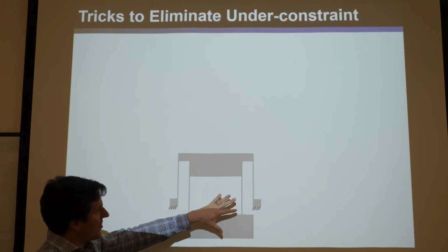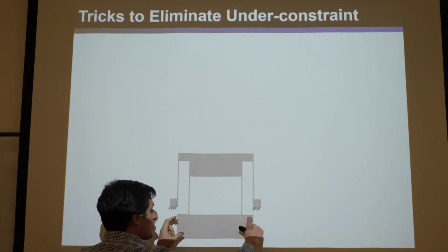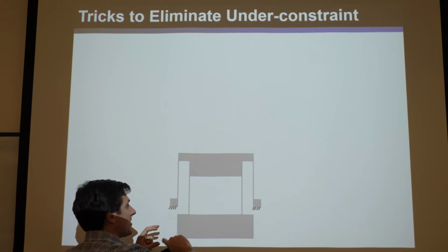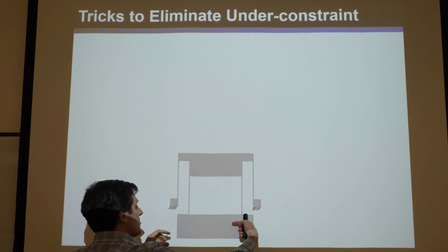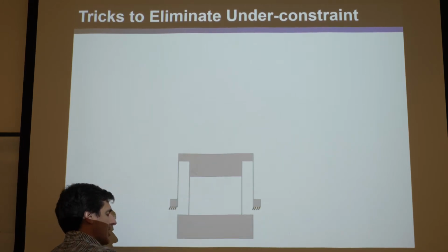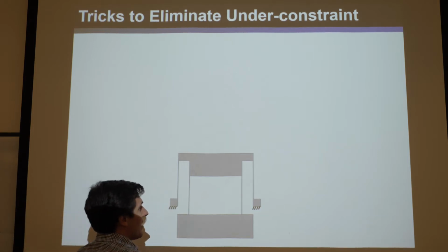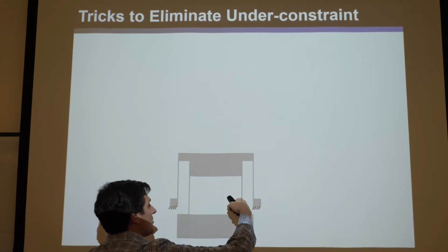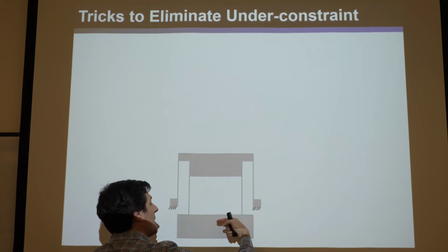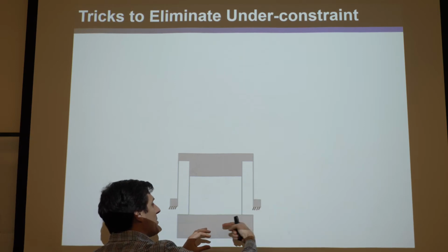But the good thing about this is that in a fairly compact space, you can achieve twice the range than you could without the intermediate body, because this goes 1 and this goes 2, because it can go as much as this and then twice as much if these are the same lengths, right? But that's only going to happen if this is forced to go 2 to 1. Because if you actually push this, it will try and snap back, and it won't be a 2 to 1 ratio.